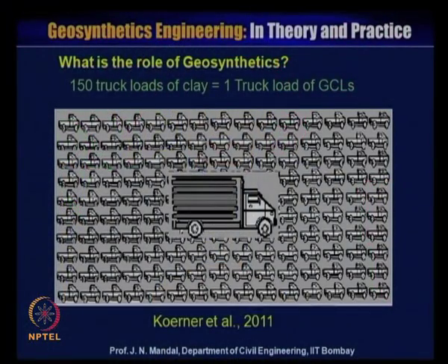You require the clay from other places, then you have to excavate, dump and compact the soil, and only then dump the waste material to form the landfill system.